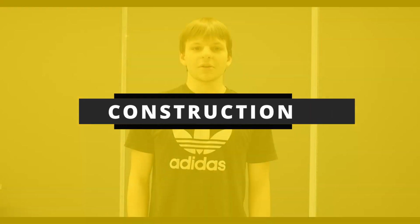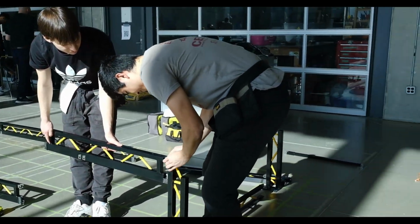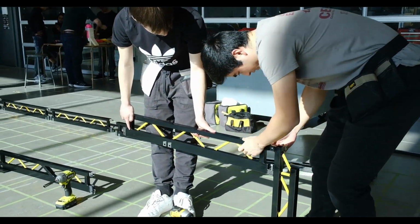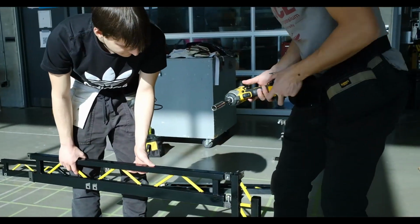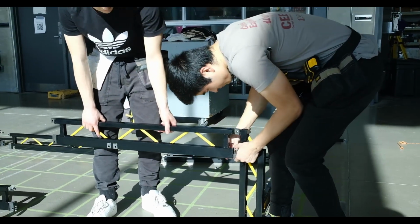The connection of our bridge is also very important in guaranteeing ease of constructability. Our wedge connection design is optimized for strength while also being very simple to slot in from a distance, while our improved triangle connection from last year is easier to align in areas with tight fits. Lateral and under truss connections were designed with crush tubes to prevent damage during assembly. Our bridge also uses wide leg plates, allowing builders to leave them freestanding during the initial periods of construction.